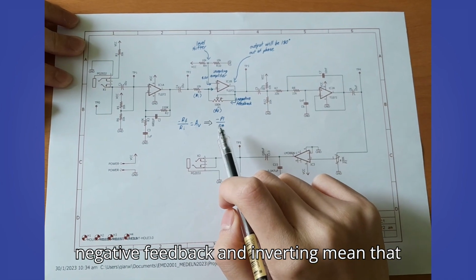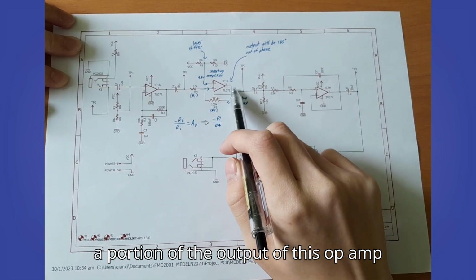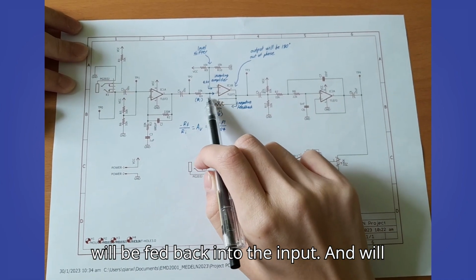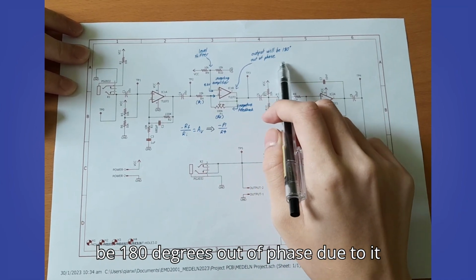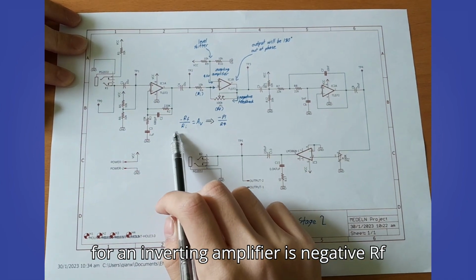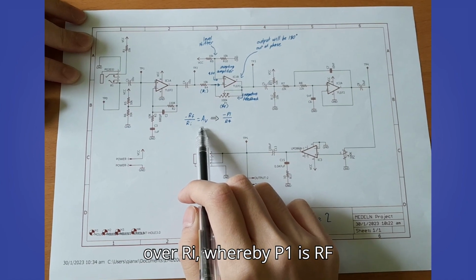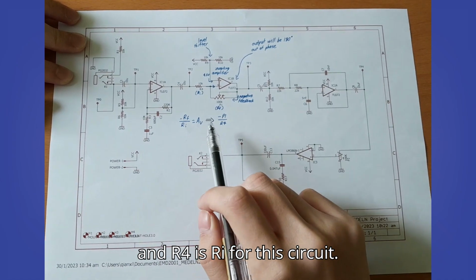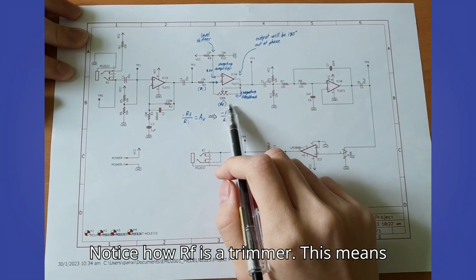The terms negative feedback and inverting mean that a portion of the output of this op-amp will be fed back into the input and will be 180 degrees out of phase due to it being an inverting amplifier. The formula for an inverting amplifier is negative RF over RI, whereby P1 is RF and R4 is RI for this circuit. Notice how RF is a trimmer.